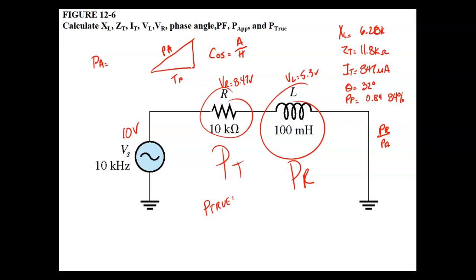That inductor is actually doing no work as far as electrical work goes. It's got a function in life, right? You understand? It's got a function in life to respond to frequency and do something that we want with frequency. But as far as creating watts, it don't create watts. It don't get hot. Resistors get hot.